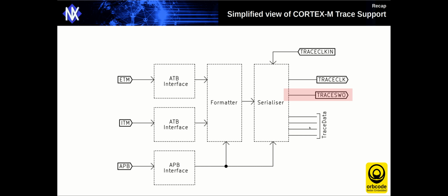The ETM flows generally have to use this alternative presentation, which is a parallel presentation with much higher bandwidth. In fact, it's parallel and DDR. We'll come on to talk about that later. But for version 1, we did not use the parallel capability. We plugged a UART or some equivalent device onto TraceSWO and use the capabilities there.